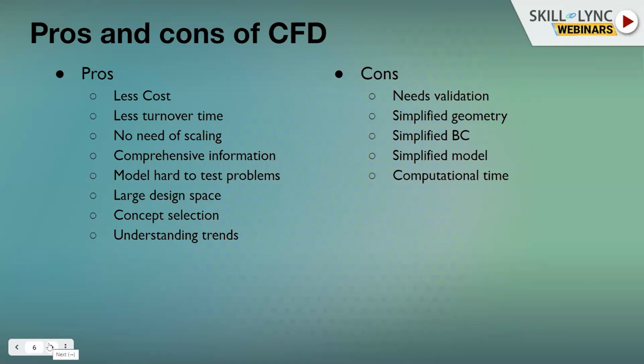The final one is the computational time. So this one could be conflicting. I put less time as an advantage, and here the computational time as a drawback. It's not suitable for all the problems, but in some problems, mostly unsteady problems and the problems where you need very accurate data, people tend to use LES kind of simulation. The computational time for solving one case can take almost a month or even more than that.